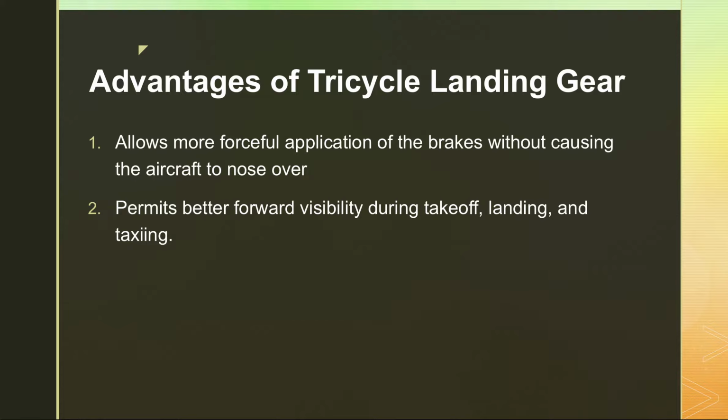Okay, so with the tricycle gear, you can use the brakes harder without tipping the aircraft over. We already saw an example of that. They give you better visibility during takeoff, landing, and taxiing. And you saw that in the video as well.